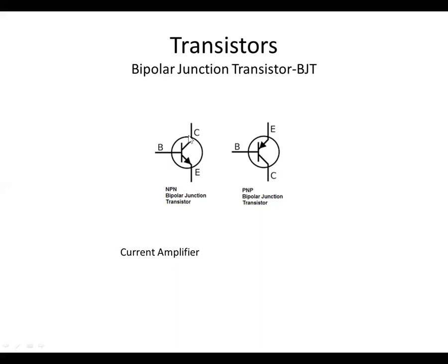It's typical of a transistor, the gain's referred to as a beta, Greek letter beta. So let's say the beta is 100. If you put 1 milliamp flowing into the base of the transistor, the collector current would be 100 milliamps. And then because of Kirchhoff's current law, the emitter current would flow here. That's what the E stands for. Then you'd have 101 milliamps flowing through the emitter. So this is the base, the collector, and the emitter.